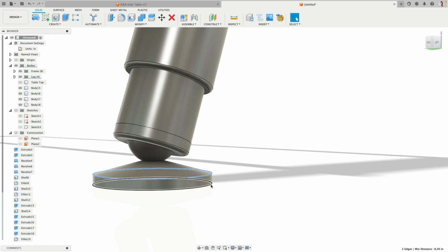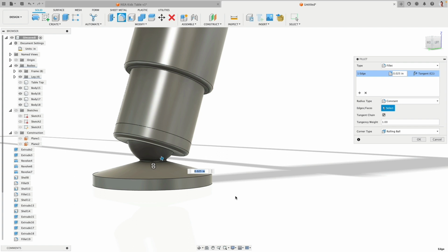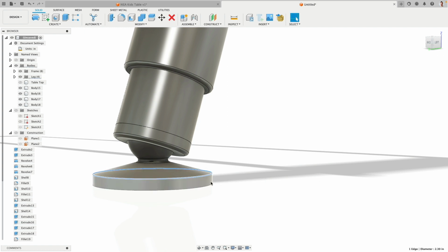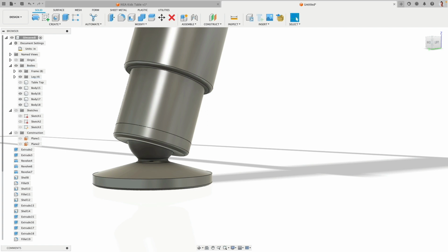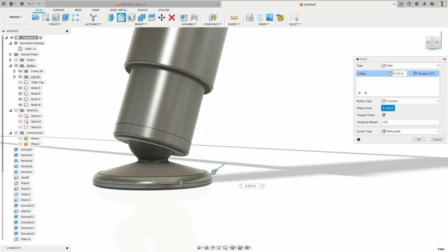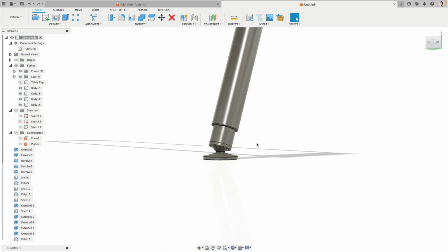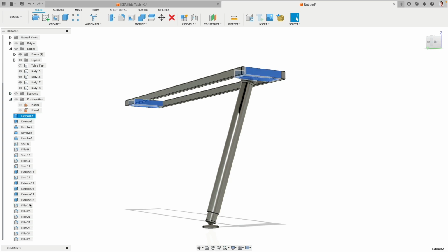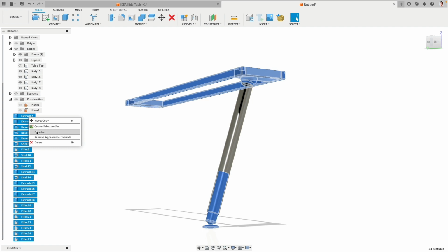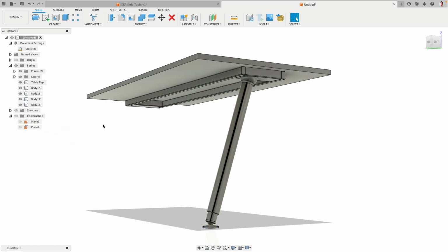And this edge, I will simply select just a little one there. Whoop. I said just a little one. 0.05. Very good. And then this one here, maybe a little bit, not too much, 0.03. The size is just really a matter of preference. 0.03 there. Beautiful. Very good. So all these features I can actually dissolve. So they're all done.